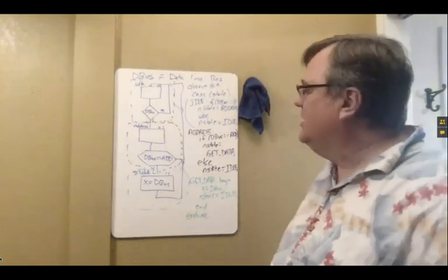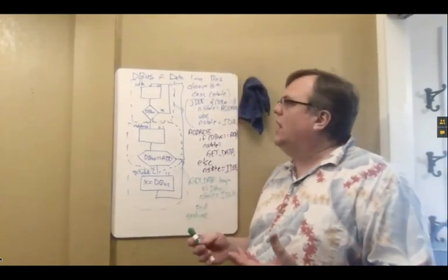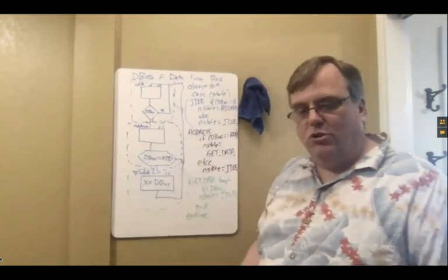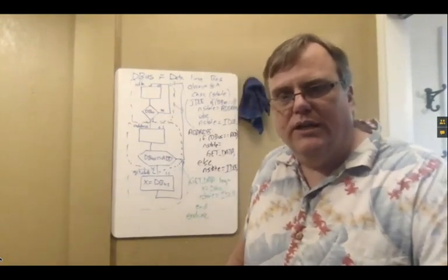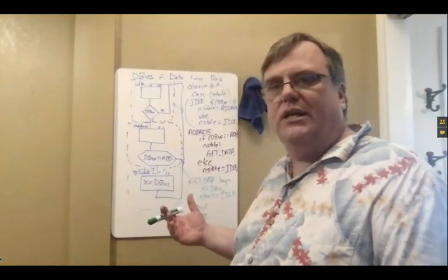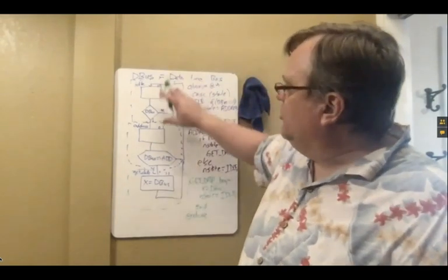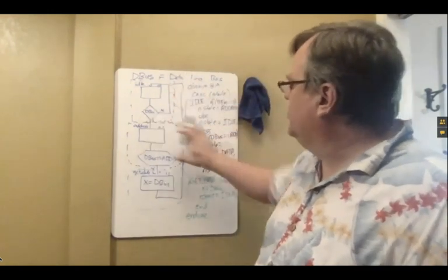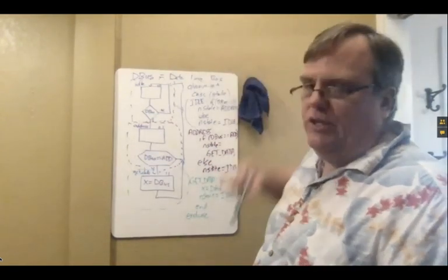So if you notice, algorithmic state machines are an extremely nice way to do design, right? They allow me to take a very complex thing. Like if I had told you, hey, look, design a bus reader inside of digital logic at the start of today, you probably would have been like, no way on earth can I do that. Well, it turned out to be a fairly simple thing. I could write it up here, condensing the ideas of them, and then it's really simple to turn it into these case statements. Whenever you do it, you will always want to do these as case statements.